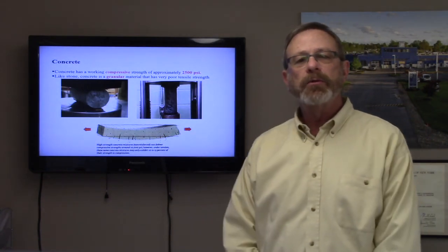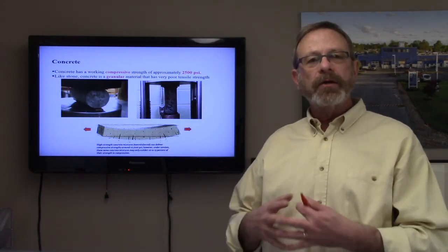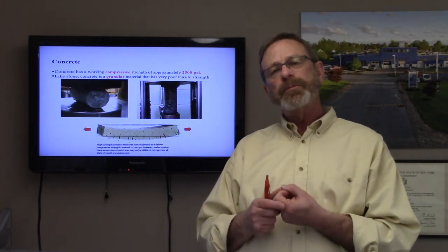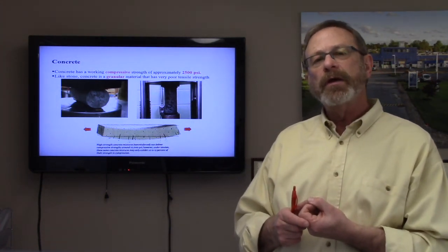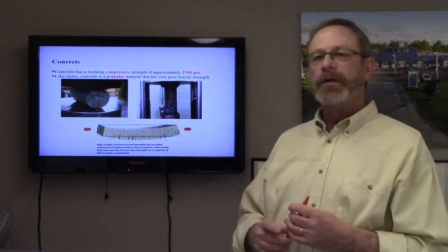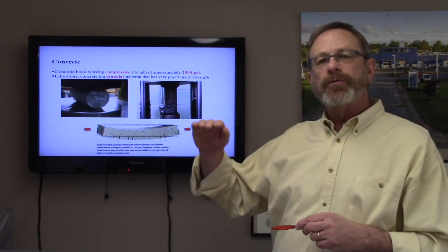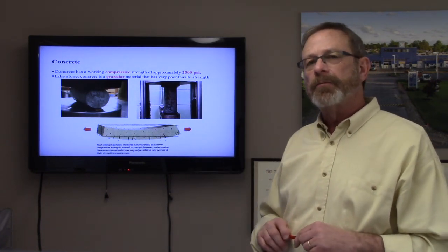Concrete is another structural material. Because it's granular, it's very strong in compression. Approximately 2,500 pounds per square inch is its working compressive strength. Here's another test being done on a concrete cylinder to see at what stress level it will start to fail.